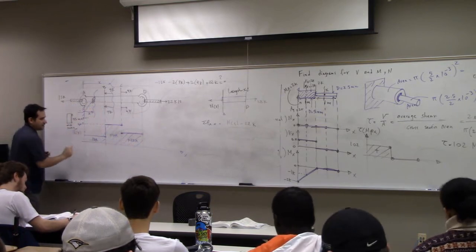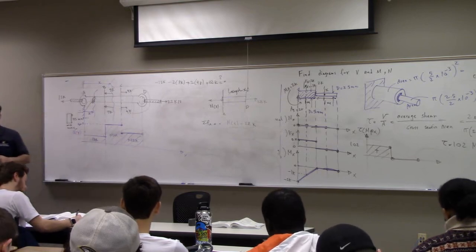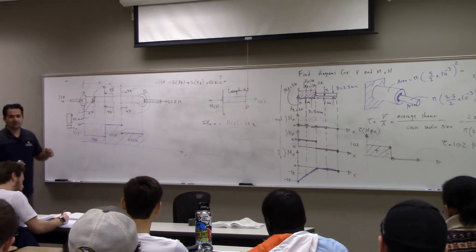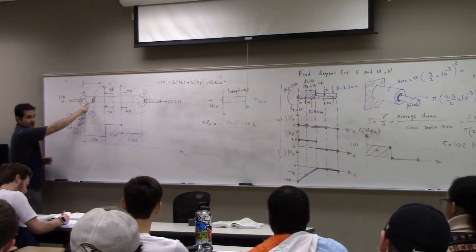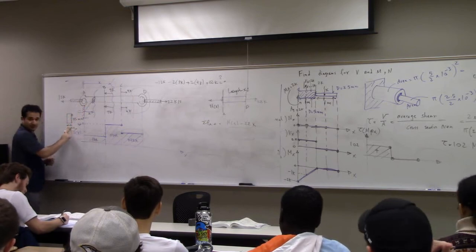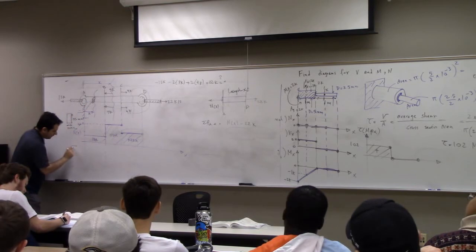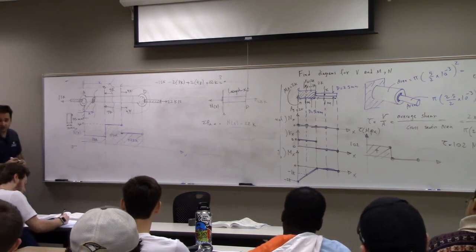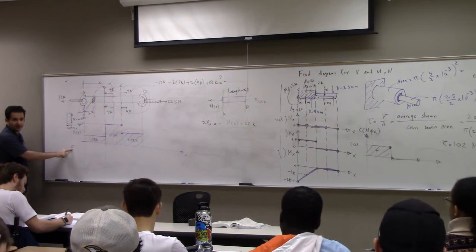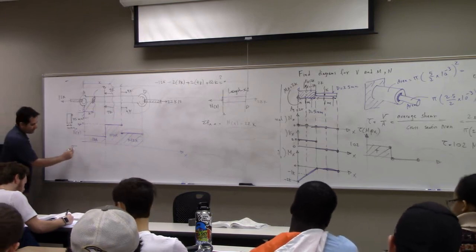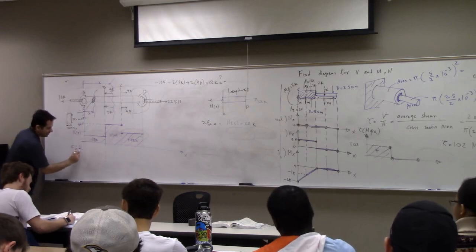If I want to find the stress, what do you do? You divide by cross-sectional area, and you notice that the cross-sectional area is the same in this case. So your normal stress, which is shown by sigma, I'll talk about it more next class, normal stress sigma is equal to Nx divided by Ax.